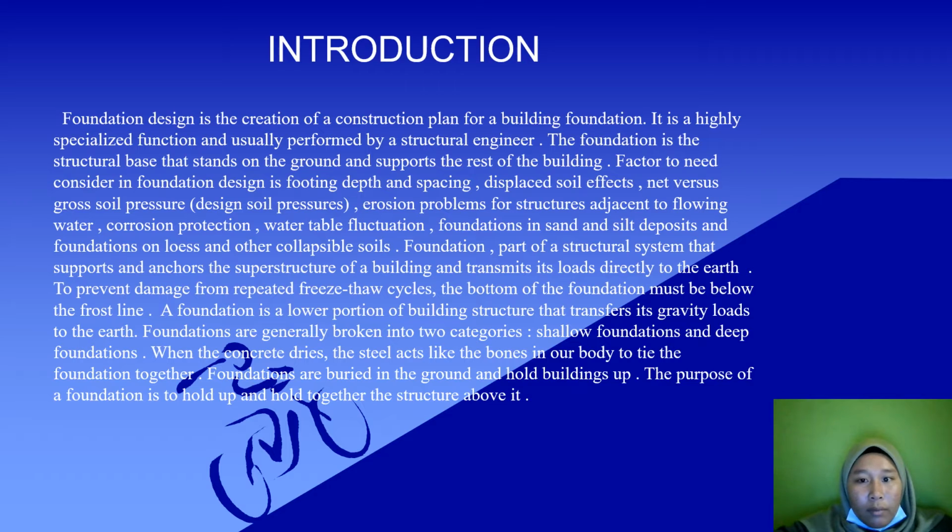A foundation is part of a structural system that supports and anchors the superstructure of a building and transmits its load directly to the earth. To prevent damage from repeated freeze-thaw cycles, the bottom of the foundation must be below the frost line. A foundation is the lower portion of a building structure that transfers its gravity load to the earth. Foundations are generally broken into two categories: shallow foundation and deep foundation.